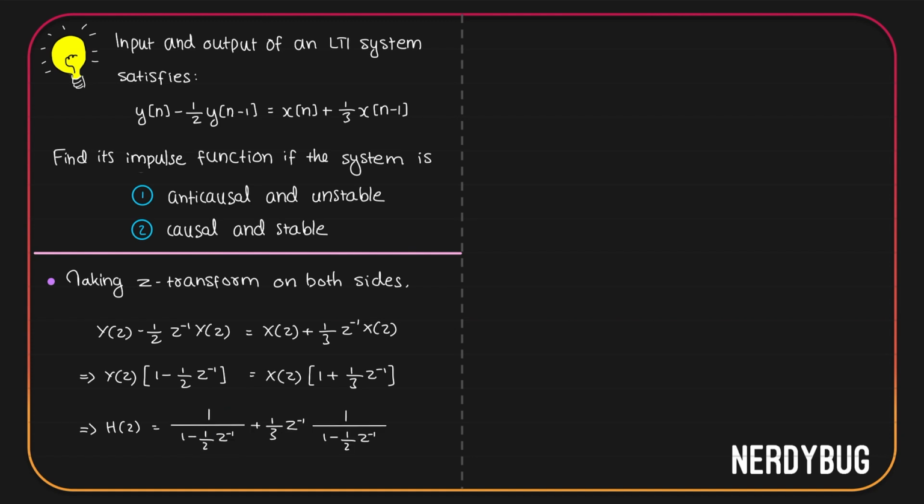Obviously, h of z only has one pole and it is when 1 minus 1 by 2 z inverse becomes equal to 0. So we can write that the pole of h of z is where z is equal to 1 by 2. Since there is only one pole, there are two options for ROCs. Either magnitude of z can be less than 1 by 2 or it can be greater than 1 by 2.